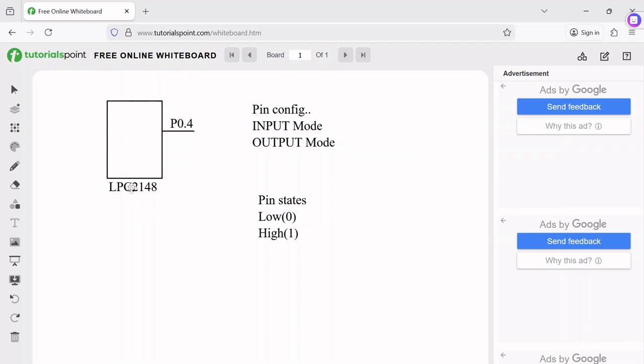So this one is the LPC2148 ARM7 microcontroller, and this is pin 4 of port 0. In pin configuration we have two modes, that is input mode and output mode. This is pin configuration. And the pin state means, is this pin low, is it acting as a low pin, or high, where high means 1 and low is 0.